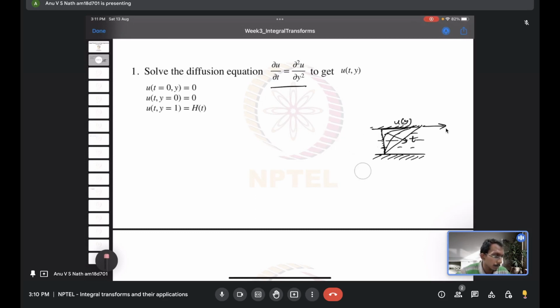Of course the reason for the momentum diffusion is the momentum diffusivity, not alpha, it's the kinematic viscosity nu, which is absorbed inside the non-dimensionalizers. That's why it is not explicitly appearing in any of these equations. So that's okay. That's just the application part.